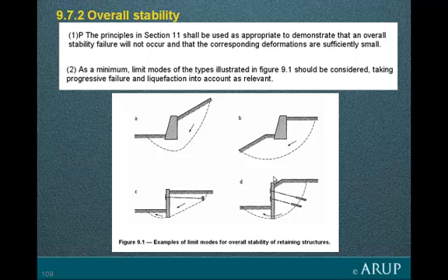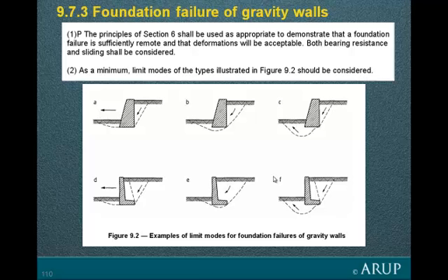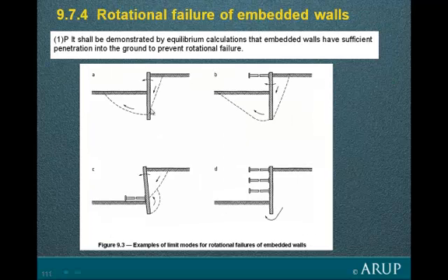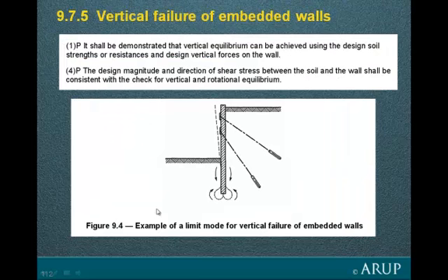These little figures have been quite popular from Eurocode 7. These are figures showing the failure modes that you're to consider, overall stability modes, more overall stability, and then the failure modes of the wall itself with active wedges and passive wedges, how it might rotate about a prop, a low level prop, and particularly vertical equilibrium. And this is where adverse wall friction starts to come into play.